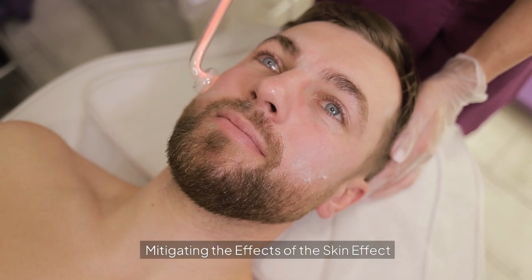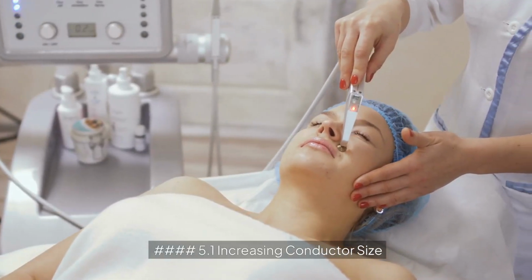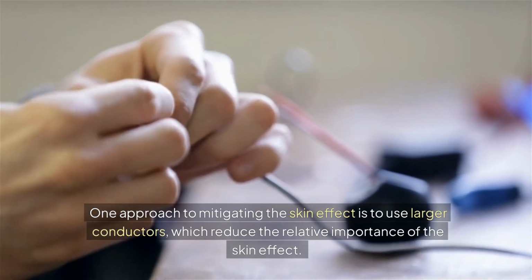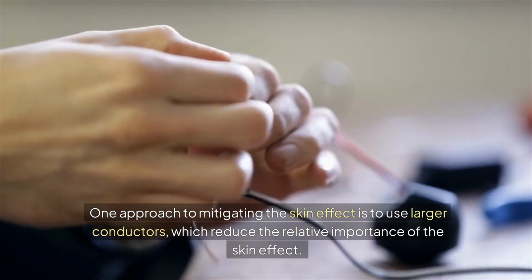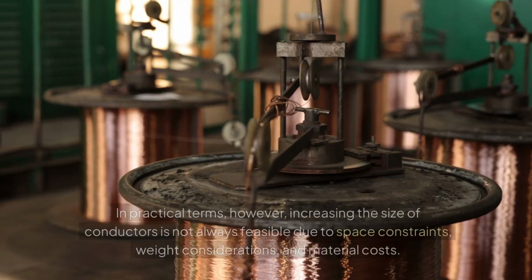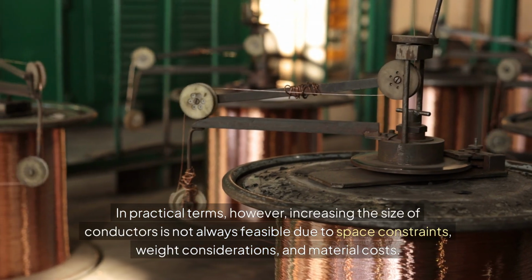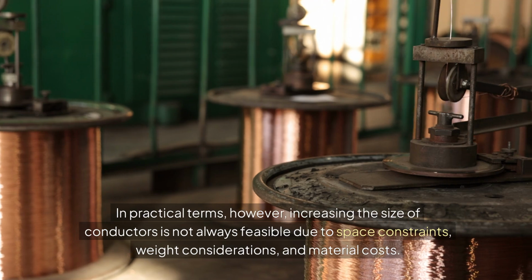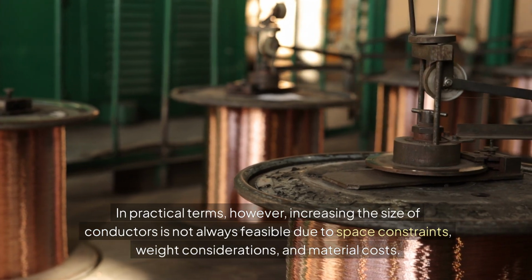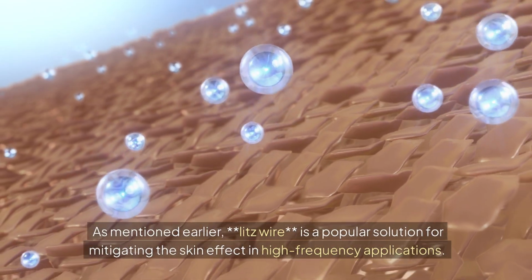Number 5. Mitigating the effects of the skin effect. Number 5.1 Increasing conductor size. One approach to mitigating the skin effect is to use larger conductors, which reduce the relative importance of the skin effect. In practical terms, however, increasing the size of conductors is not always feasible due to space constraints, weight considerations, and material costs.